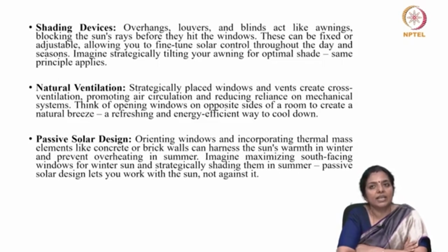Use of natural ventilation happens when windows and vents are strategically placed to create cross ventilation, promoting air circulation and reducing the reliance on HVAC systems. The dynamic envelope can comprise components which can streamline and direct wind movement inside the buildings. One must definitely not forget to adopt the principles of passive solar design.